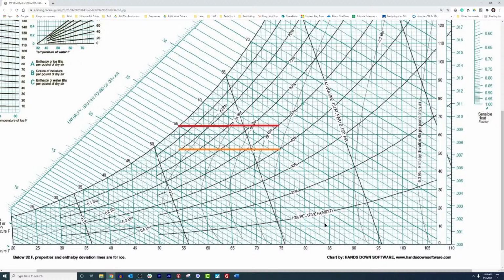So if I have a choice to use a return temp, right, of let's say 75 degrees at 30% relative humidity or 65 degrees at 50% relative humidity, and that's outside air, I am introducing significantly more moisture back into my airstream, and that will make people feel muggy, it'll make people feel hot, it will make the transfer and the cooling less effective because we're introducing more enthalpy. That's why you'll see enthalpy used as a comparison for economizer enable. You'll see dry bulb and you'll see enthalpy.